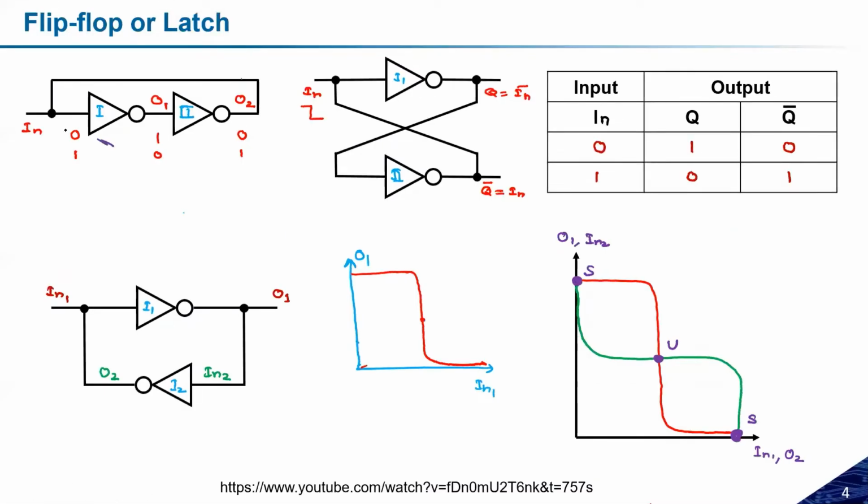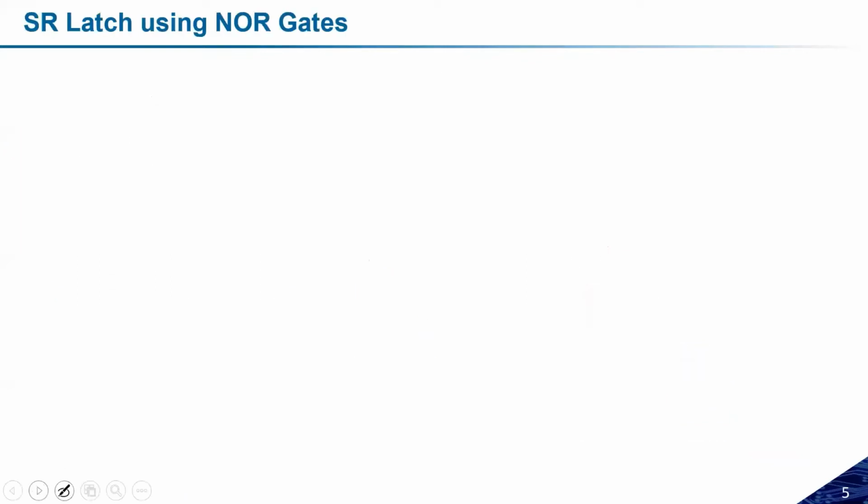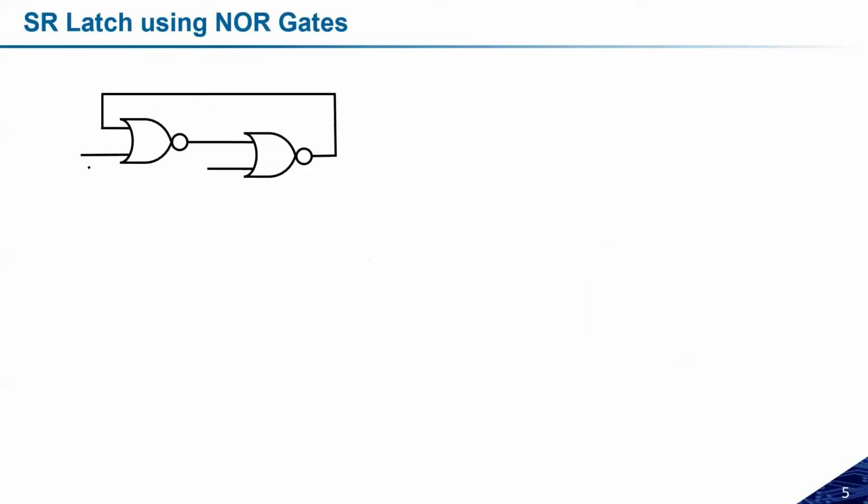but the same input there we will be unable to control, because initially if I have kept it at logic 1, then I need to remove it, and then it will work as a latch. But if we are utilizing two-input logic to design this, you do not need to remove it. Based on the states of these inputs, you can decide what kind of logic to hold. This is why NOR or NAND kind of structures are required to really make the latch. Based on these states, you can control the outputs.